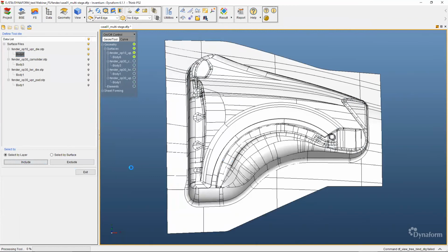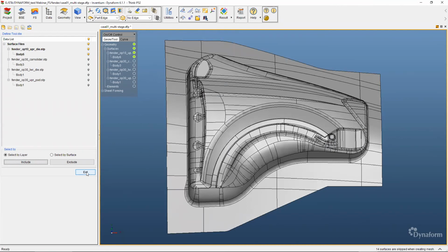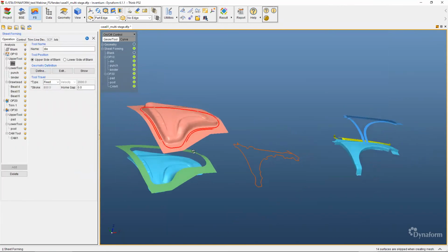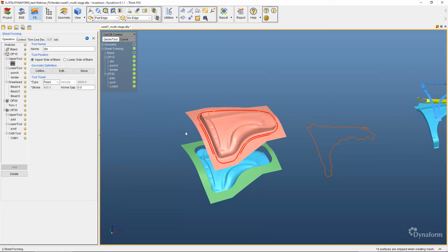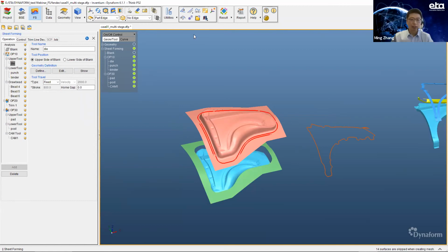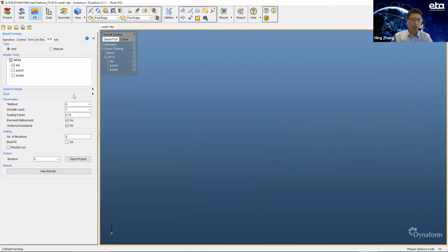We have another question from our partner asking about the best fit. Is it possible to do a best fit of the geometries before plotting the residual deviation in SCP? Oh, yes. There's one option called best fit. So before we start running the Springback compensation, we are able to fit the result after Springback with our original geometry. It will provide you a better result for running this compensation.